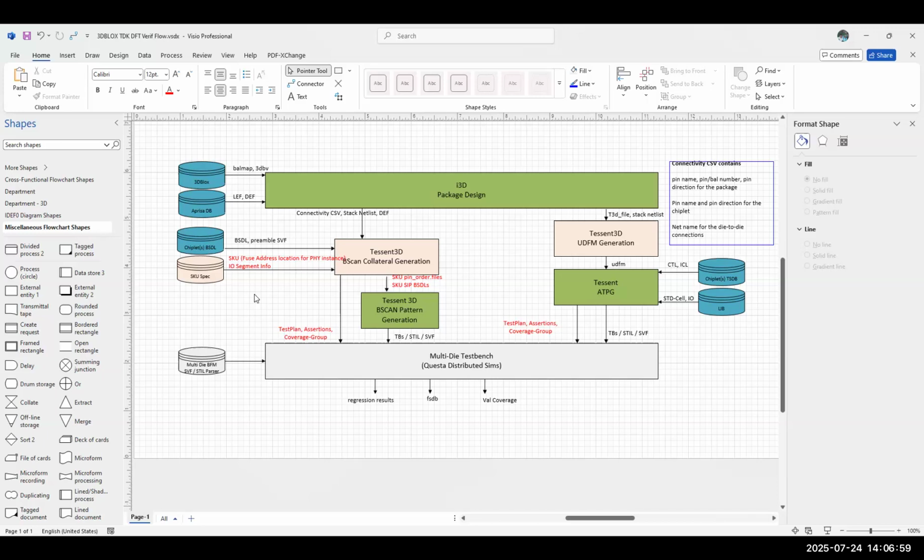But you can't just give the pins and that's it, right? There's other. So yeah, the fuse blowing is another topic, Tony. For this validation effort, what we are looking at is, normally they have an address mapping of two different locations. One for blowing the fuse, which they call the write address for that fuse of that IP instance.